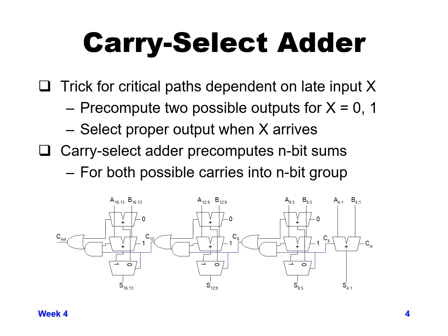So as your carry is propagating through, you can see in the diagram below, for each group of 4, we're calculating 2 separate sums. We're calculating one sum on the top adder of each group of 4 that is assuming the carry in is a 0, and we're calculating a different sum on the bottom shown row of sum signals as if the carry in was a 1.